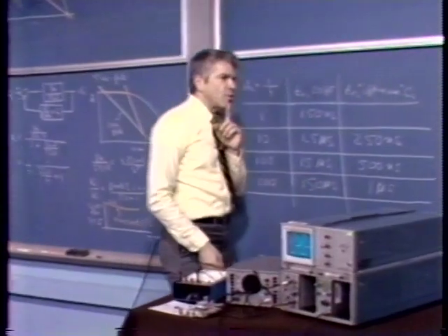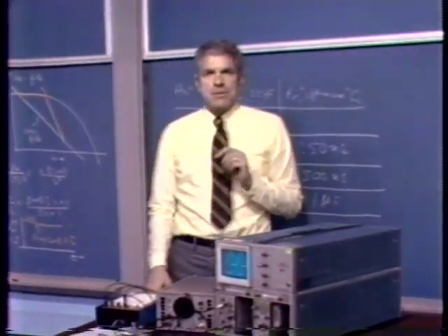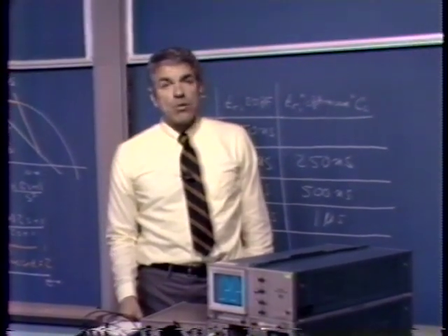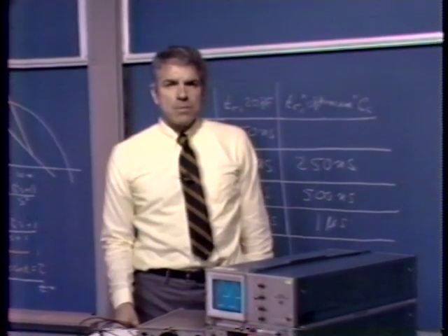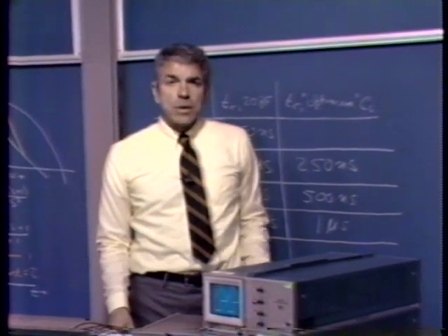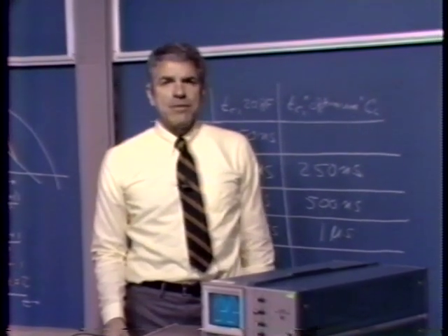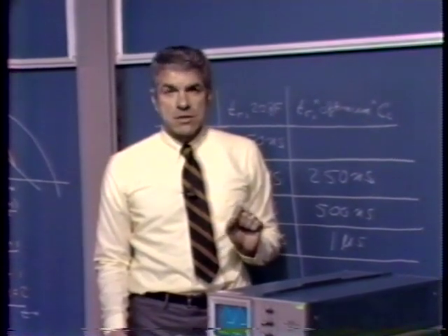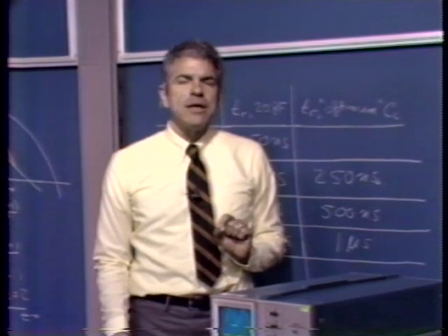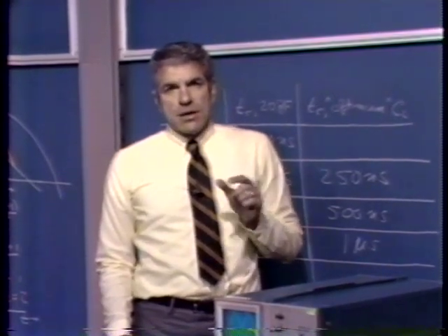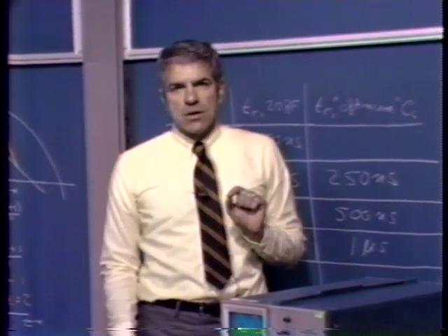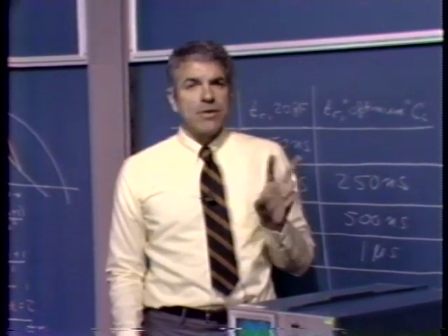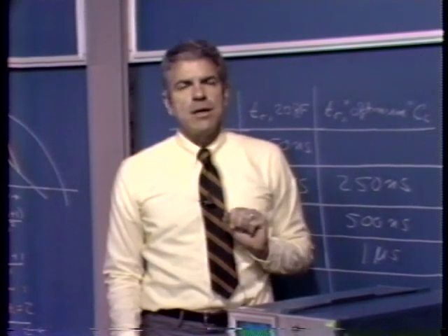Well, let's see. We said that when we use single pole compensation, the open loop transfer function of the operational amplifier over a wide range of frequencies is proportional to 1 over S. That's what we mean by having a single pole roll-off. The amplifier looks sort of like an integrator from its differential input terminals to its output. Or alternatively, the output voltage of the amplifier is the integral of the voltage applied at the very input terminals of the amplifier, not the input of the overall feedback loop.